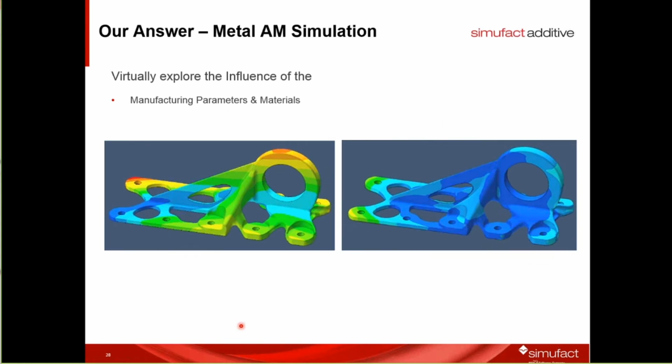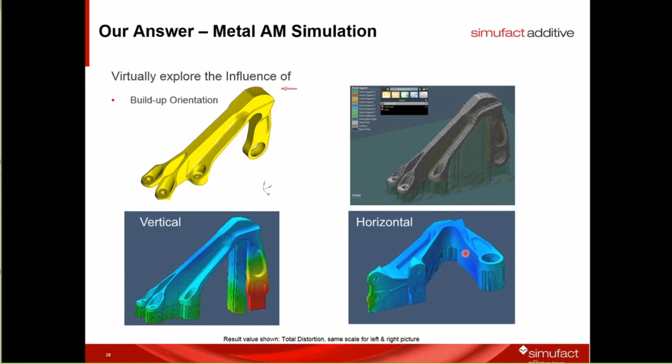So when you do that, you could take a part, such as this aerospace bracket, and say, I'm going to have these parameters, therefore it's this set of inherent strain, and I get this simulation. And I'm going to set my parameters differently, use a different inherent strain, and I'm going to get this configuration. And in fact, this configuration results in lower deformation.